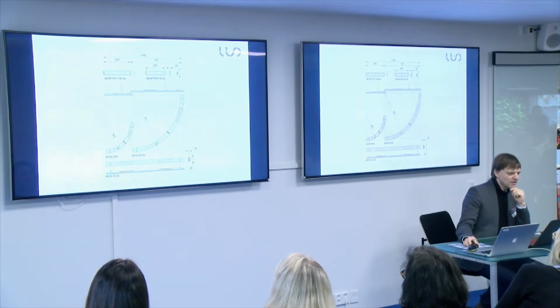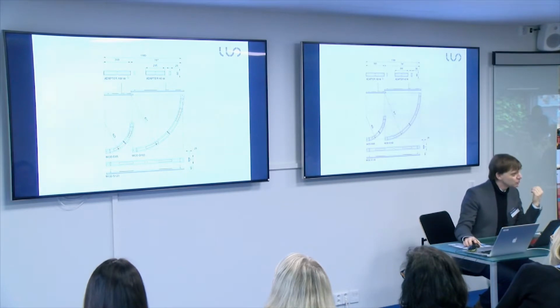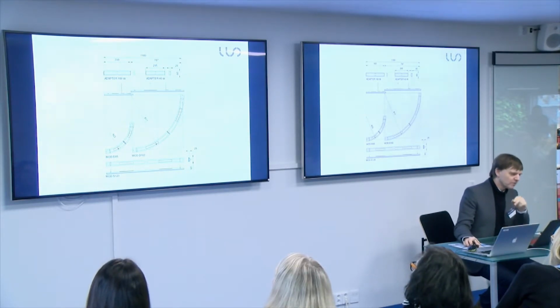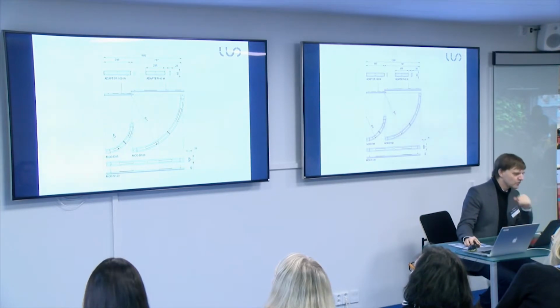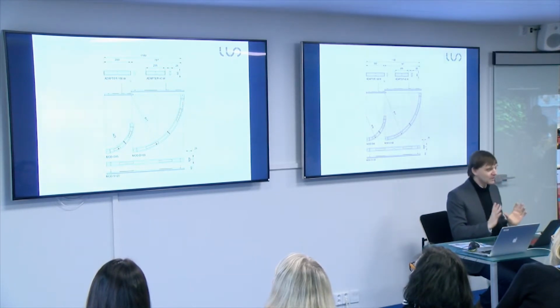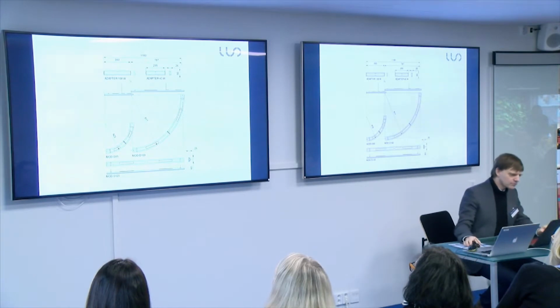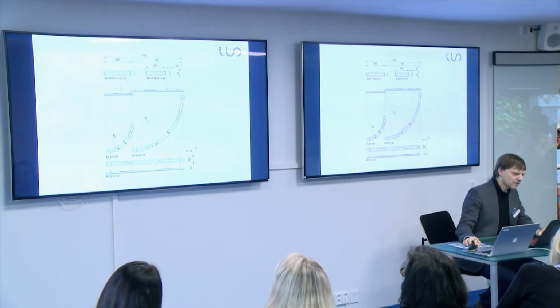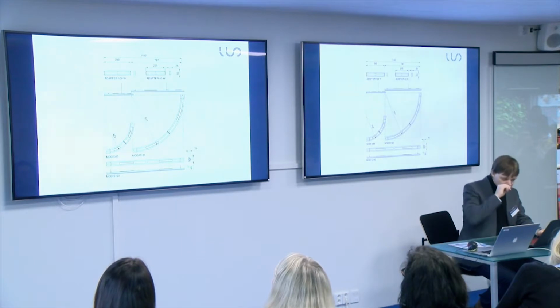It starts actually with a module which hosts the power supply and the lighting control. We call this the master module, the first module. It's 100 watt, and probably we are going to skip the 40 watt, so we are speaking now only of 100 watt. And all these elements are in a modular system, which is oriented after the longest straight module, which is 1 meter 18 centimeters long.